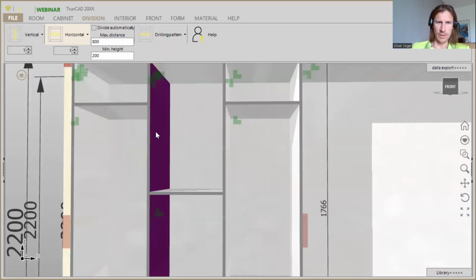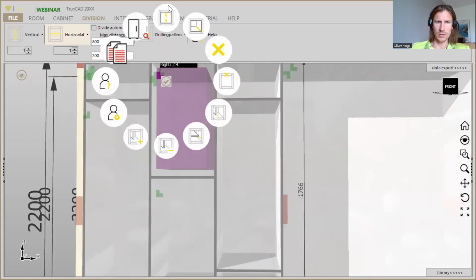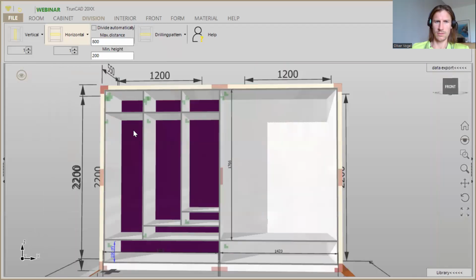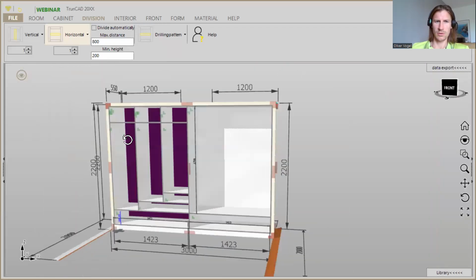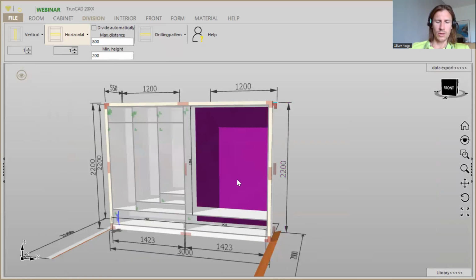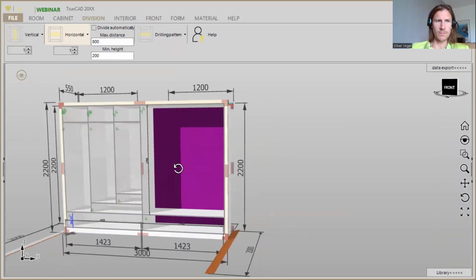And here in the middle area, we are doing the same. Just click on the right smart click, on the height, type in 250 and confirm it with enter. So that's well done.